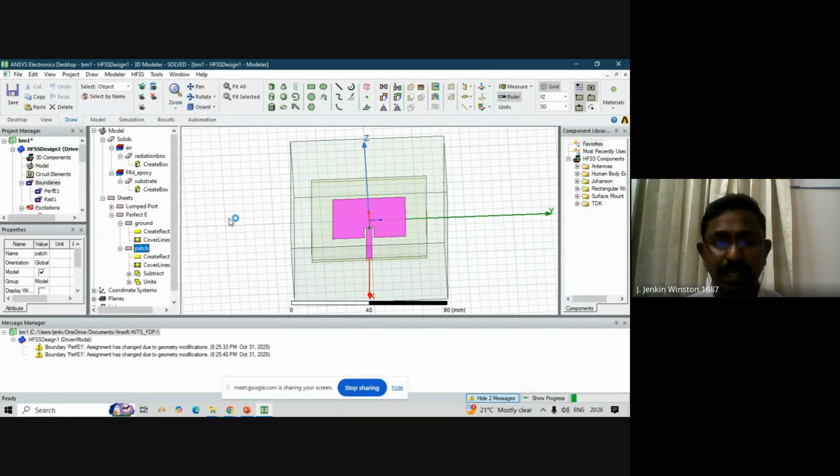Like here I've taken patch length, patch width, and insert length. So this insert length I will first take as 0.5 times the half of the patch length, then 0.6 times, and then 0.7 times. Like that for 2.4 I will do. Similarly, I will do for 2.5 and then 2.6. I think this model itself is taking some time. So I'll wait. Okay, so this is complete.